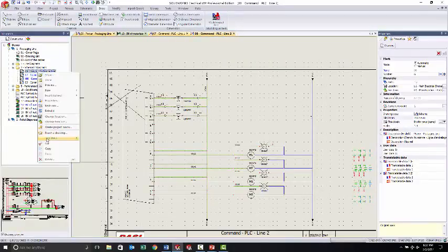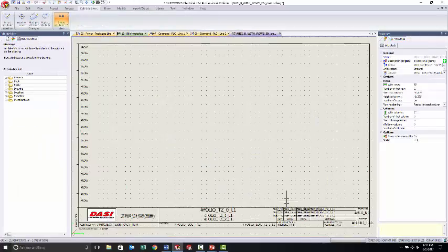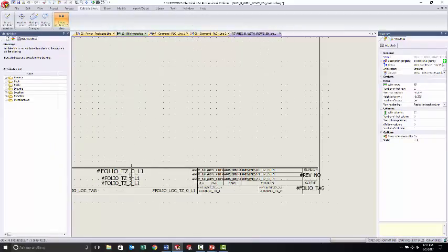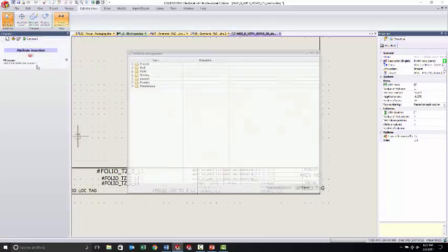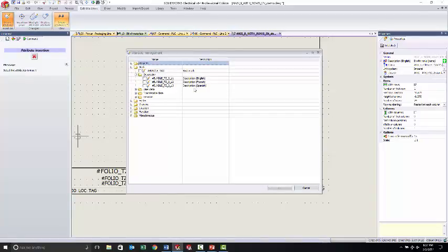All right, so I was talking about title blocks. We were inside the title block. We went off on how you can do some other good fun stuff here. So let's open up that title block again. Because, of course, as you see, this title block looks pretty darn foreign. In the past, I've always said, okay, I can cheat by opening up Insert Attribute and see what the attribute description is, but it was never very easy for me to find. I was always trying to search for specifics.